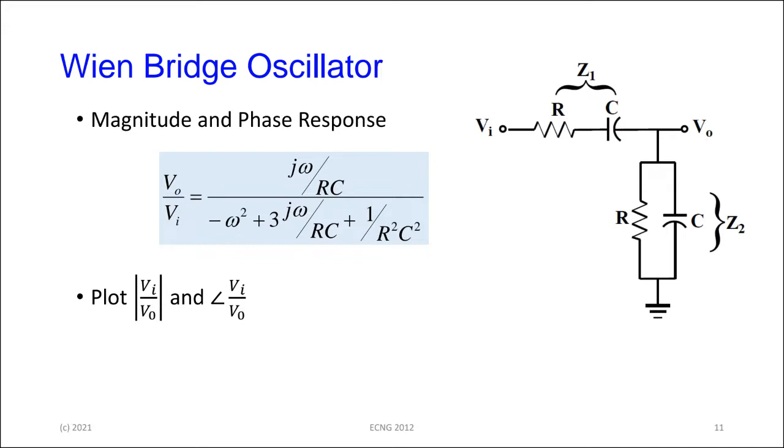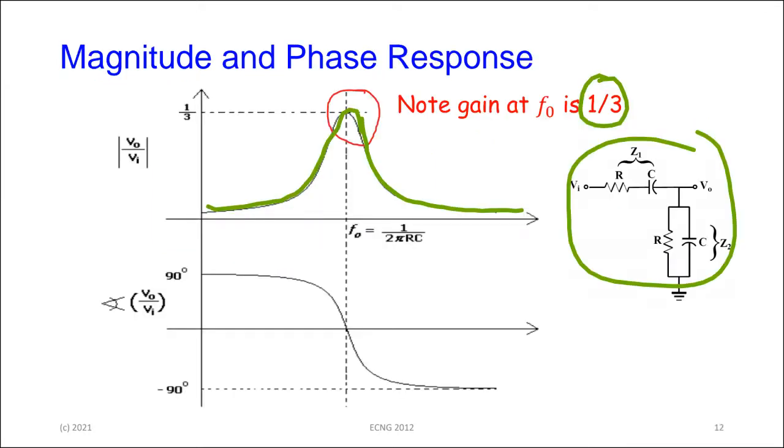You have the real part, which is these two here, and the imaginary part here. The inverse tan of that will give you what the phase angle looks like. And if you were to plot the phase angle for this second order system, it is going to start at plus 90, as we have here.